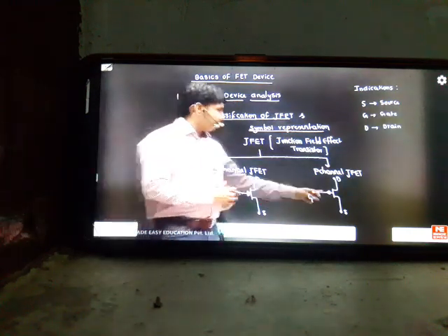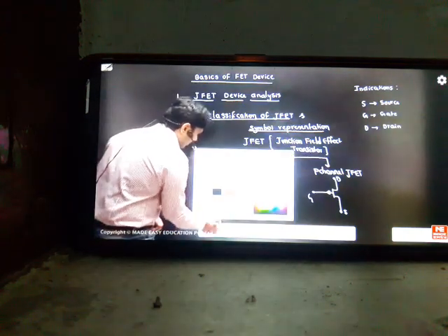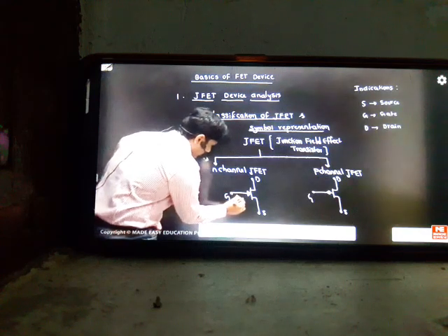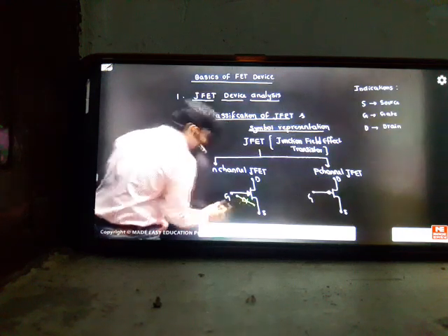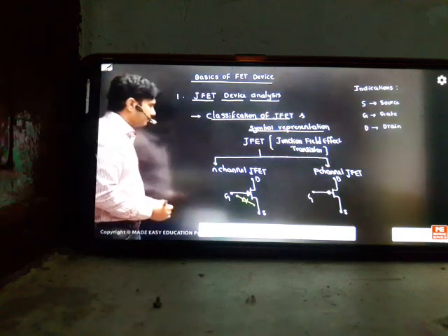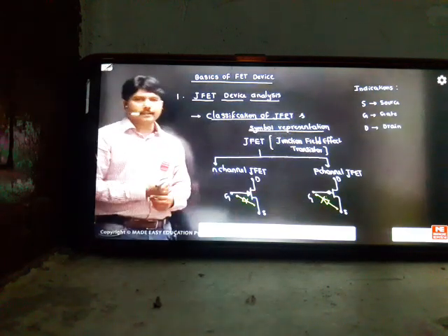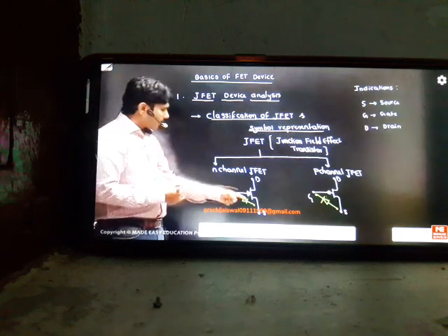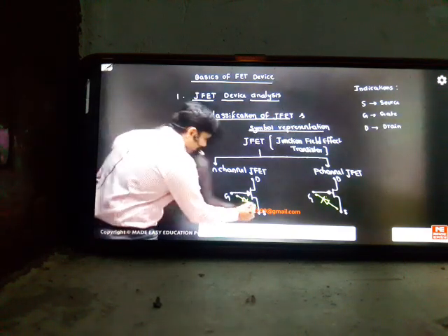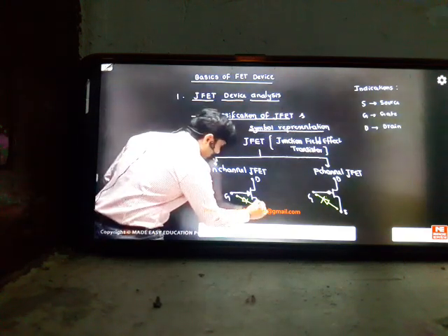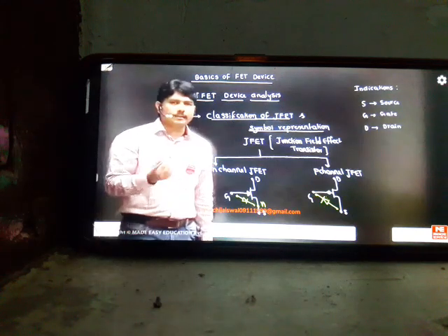So what is the meaning of this arrow? The trick is very easy. You can see the trick. The diode contact between gate and source is like this. Gate to source, the diode is indicated. That means there is a P-N junction between gate and source. So this diode direction explains the arrow indication. If the diode is in the downward direction, the arrow should be inward, such that this material becomes N material. If the source becomes N material, it is called an N-channel JFET in electronics.